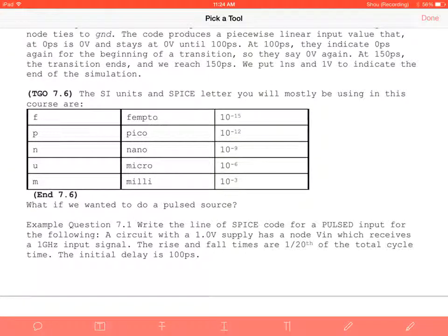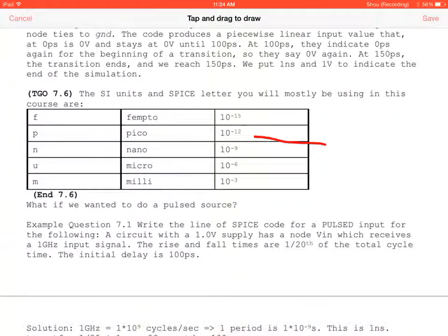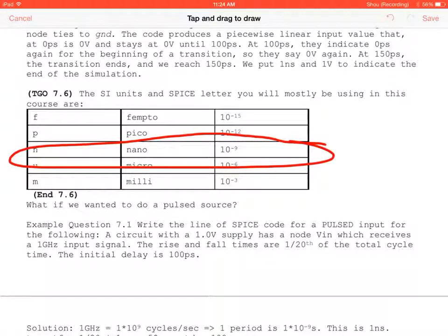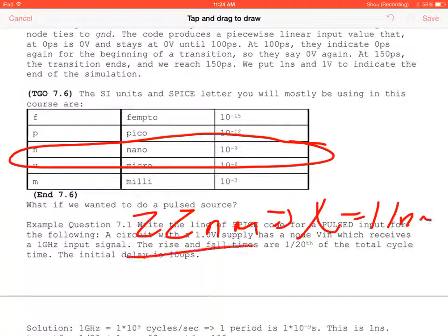So the reason this is important, especially when you're dealing with nanotechnology, now we understand what that means, like 22 nanometers, therefore our lambda is going to be 11 nanometers, 22 nanometers is the size of the poly, and so on.